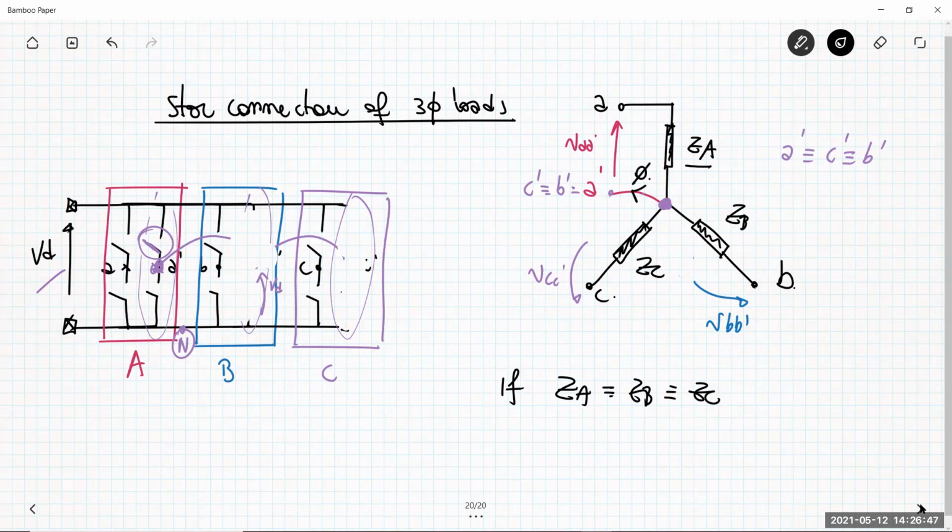This is one of the situations exploited for three-phase load systems. It means that the leg A prime, the only leg that remains after eliminating the redundant configuration in parallel, can be totally eliminated, because no current is provided by this leg. So it acts like an open circuit, and if I have an open circuit, I can eliminate it from my discussion.